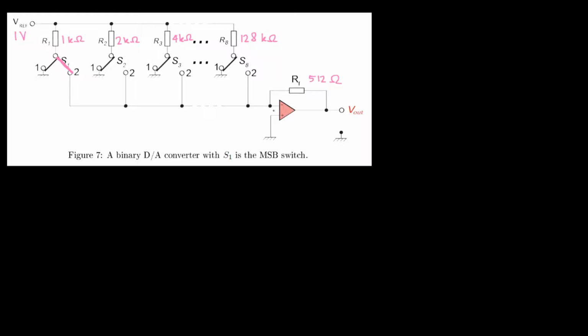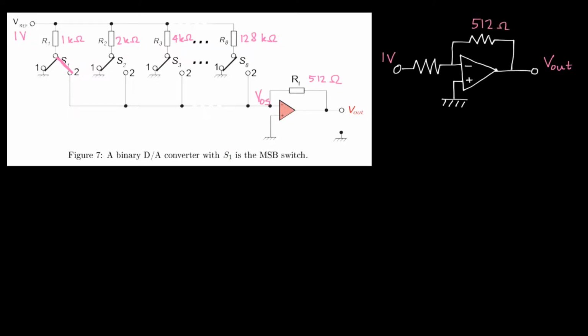The final bit of information that has been given to us in the question is that we have a non-ideal voltage offset at the input of the op-amp, meaning that the voltage at the non-inverting input will be VOS. Given that we only use the most significant bit as the input to this DAC circuit, we can redraw this situation as the following. And finally, the potential at this non-inverting input will be VOS, and that is a non-zero offset voltage. With this situation, we can set up a nodal analysis equation at this inverting input. That will give us the following.